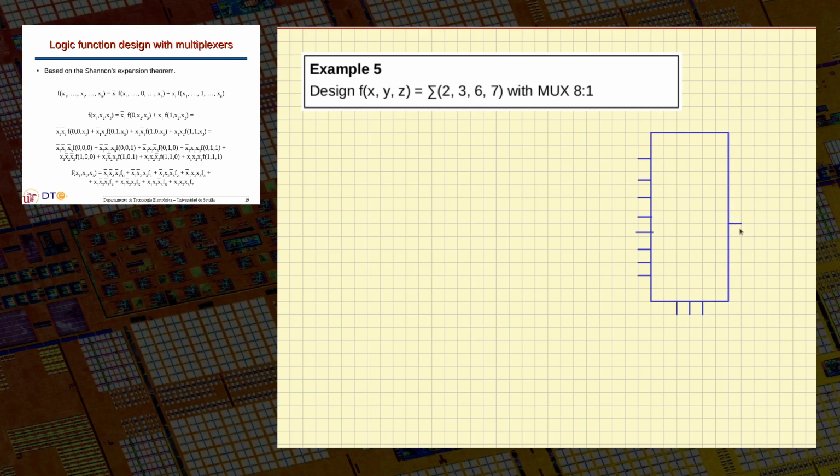Okay, so first thing, I will mark this one. This is MUX 8 to 1. Because we are drawing simply a square box, we need to put a name to indicate what device it is, because the shape doesn't inform about the device. Now I number the inputs. I number the selection inputs 2, 1, 0. It's very important to put the numbers so I know what are the most and the least significant inputs. Okay, and the data inputs: 0, 1, 2, 3, 4, 5, 6, and 7.